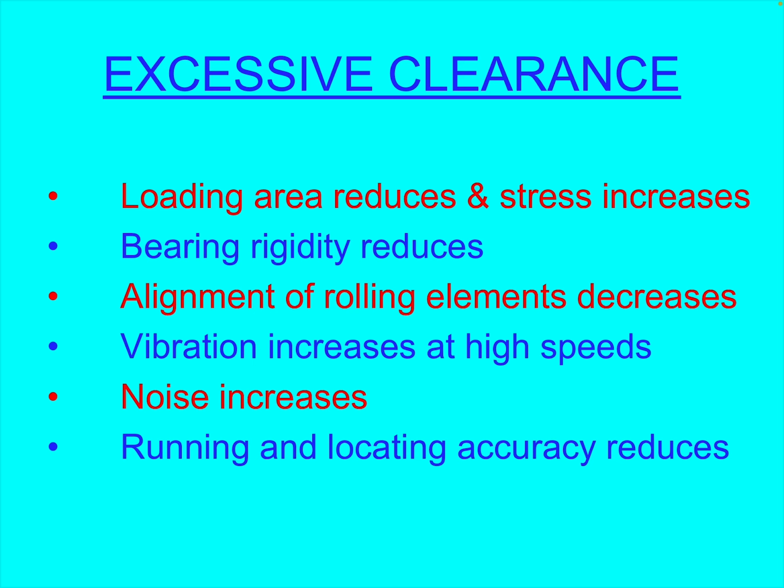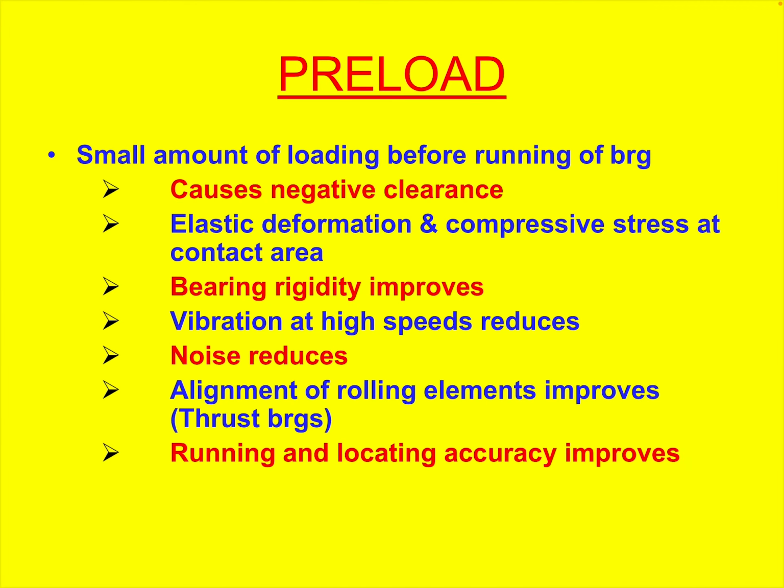Excess clearance reduces thrust engagement in the bearings. Alignment of the rolling elements is degraded. Vibration increases at high speed, noise increases while running, and locating accuracy reduces.